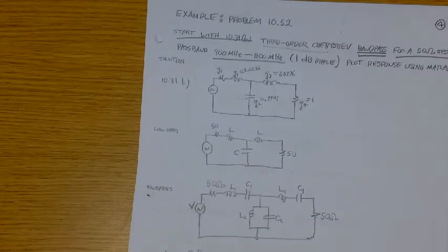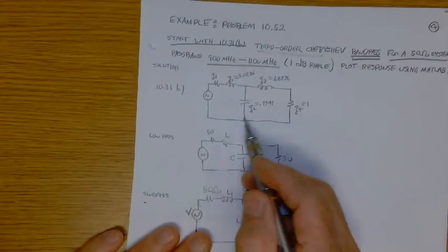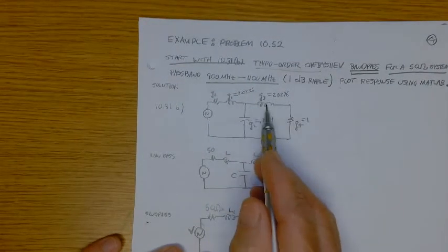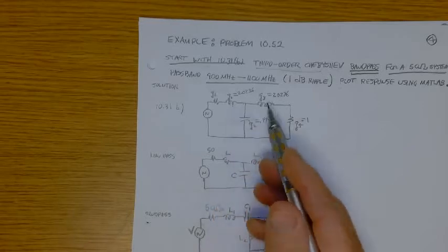Okay, right. So the low pass design is LCL. Let's go quickly remind ourselves how this works. First, I designed the low pass design, and I'm wanting a 1 dB ripple, third order. So that puts me in the middle table, third order.